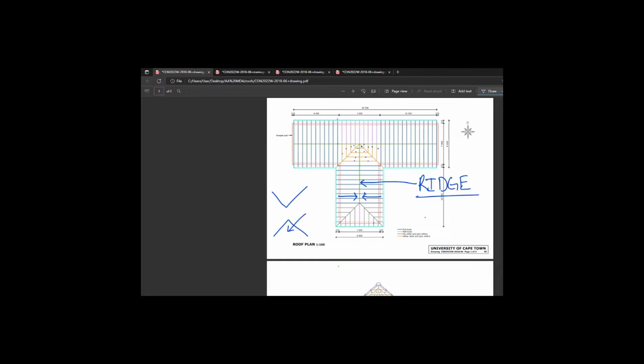But until we get to here, and we start saying, how are these jack rafters supported? If you weren't aware of it, you would say, well, there's a green line there, it's fine. They are supported. That green line is nothing physical other than an apex, telling us the shape of the roof. There is nothing supporting them. You have to account for it, and you call it a ridge beam.